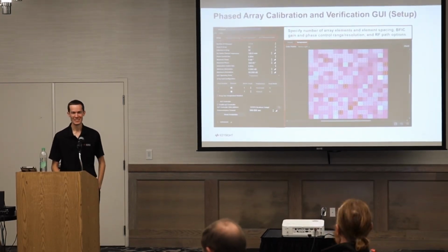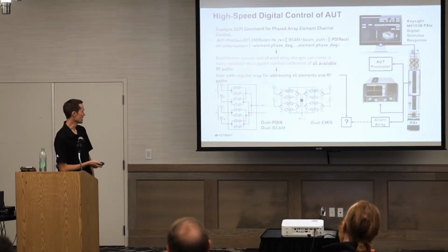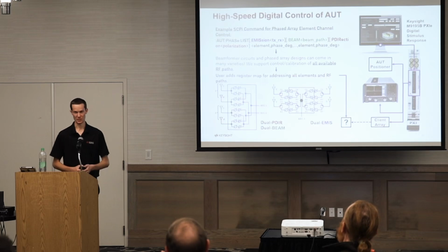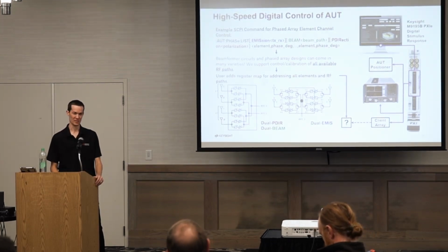Yeah, thank you, John. So it's a kind of language for sending commands to various instruments. As I said, a good comparison is a network analyzer where you can set the frequency span or the power level. So we're developing a SCPI parser now for a generic phased array. Initially, we're supporting rectangular arrays, but we'll eventually expand that to other geometries, layouts, and lattices.